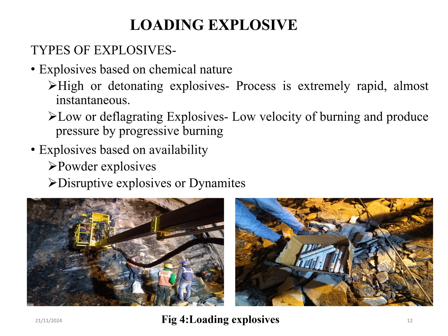Loading explosives. Explosives are loaded into the drilled holes to break the rock. There are different types of explosives based on their chemical nature and availability, such as high or detonating explosives and low or deflagrating explosives. The choice of explosives depends on the specific requirements of the tunneling project.